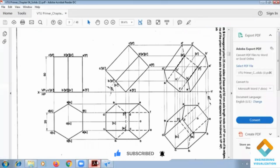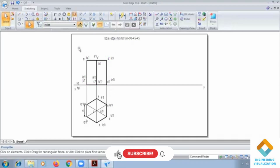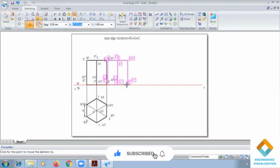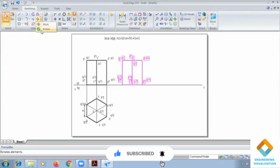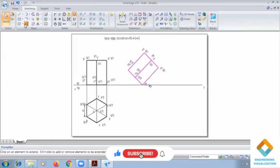Okay, so now 45-degree inclination to HP. So we are going for base edge inclination. So we have to incline this with respect to the base edge. Okay. Angle of 45 here. Then extend.